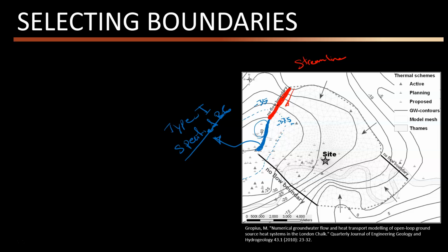But again, the thing that you need to be careful with is that these potentiometric surfaces move. For example, if this is the information for 2010, and you look at the 2015 map, then you'll see that the -40 line is, for example, something like this. So it has been moved or shifted, which is highly possible because this is a transient system.